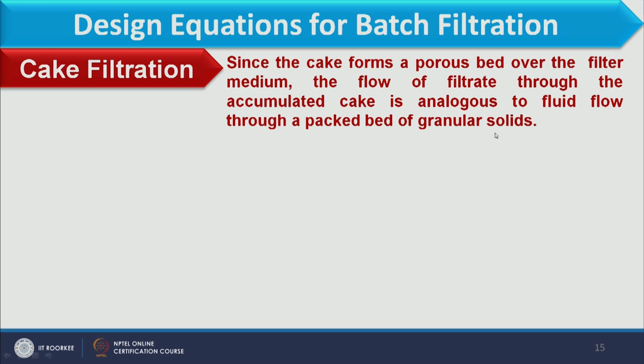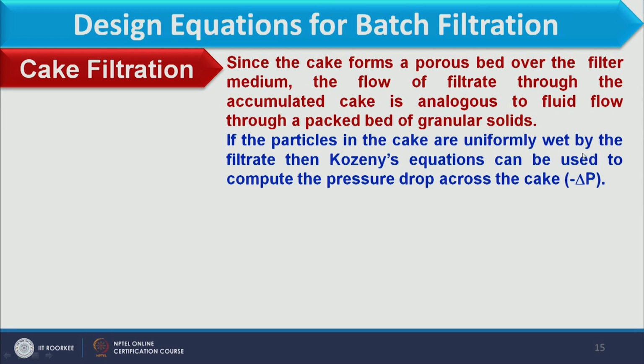So, when we consider the filter media where we have accumulation of solid particles, when liquid passes through the voids in between the particles, that resembles the condition where fluid passes through a packed bed of granular solid. So, if the particles in the cake are uniformly wet by filtrate, then Kozeny's equation can be used to calculate the pressure drop across the cake, because here we have assumed that the bed is completely wetted with the liquid. So, we can use Kozeny's equation.